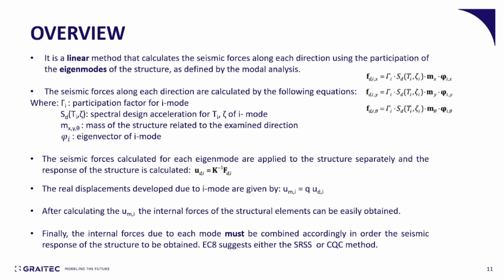A quick overview of this type of analysis. It's a linear method that calculates the seismic forces along each direction using the participation of the eigenmodes of the structure, the ones we defined earlier using the modal analysis. The seismic forces along each direction are calculated by the following equations, the ones we see on the right-hand side. And let's see what those parameters stand for.